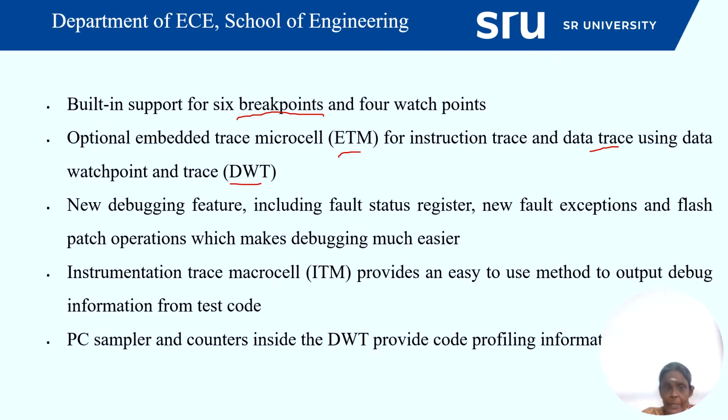And new debugging features including fault status register, new fault exceptions, and flash patch operations, which make debugging much easier. And one more block, instrumentation trace macrocell. This ITM is a built-in hardware peripheral for advanced debugging.